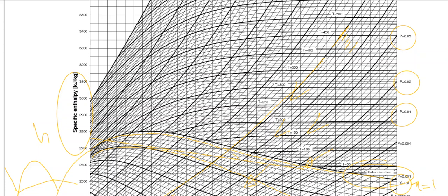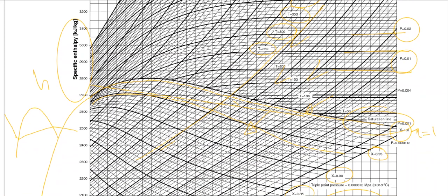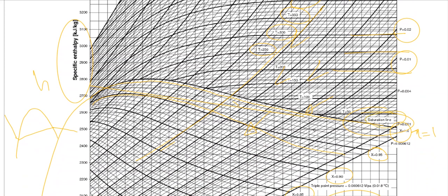Now there are other lines, like for example these lines over here. You can just check it, on the top of the lines there are some values given, and that means these are the temperature lines. And yes, similarly the temperature lines are also divided into sublines as well. So 3 to 4 distant line what we have seen over here, these are the saturation line, and inside the vapor dome we can actually find the saturation line at different dryness fraction.